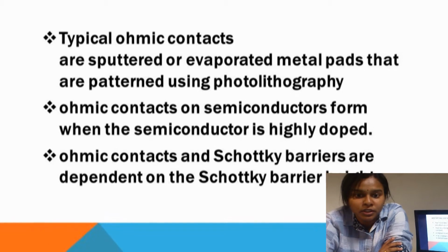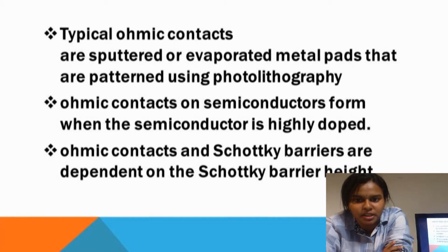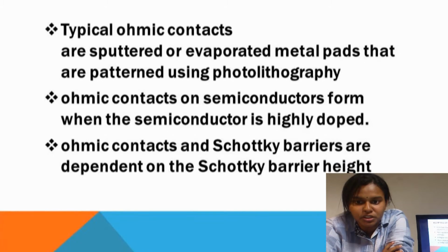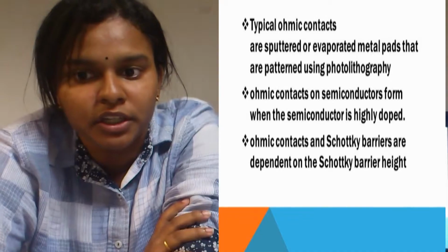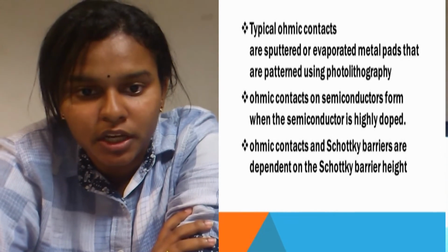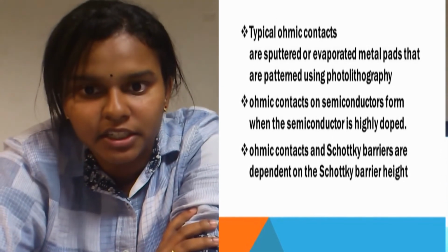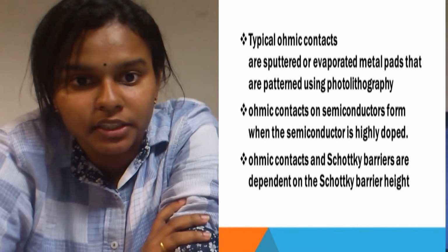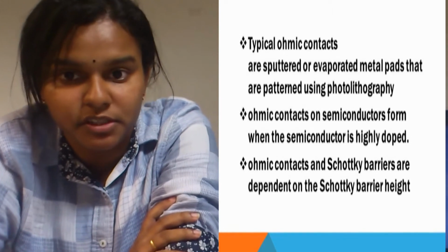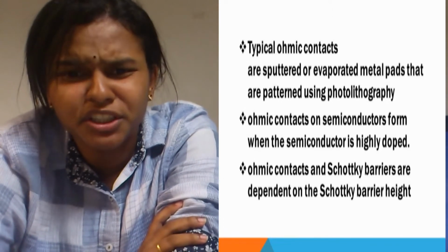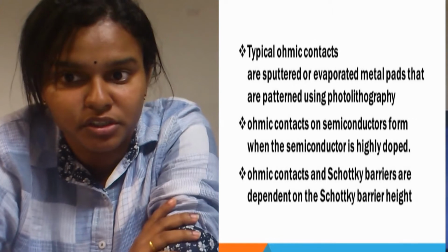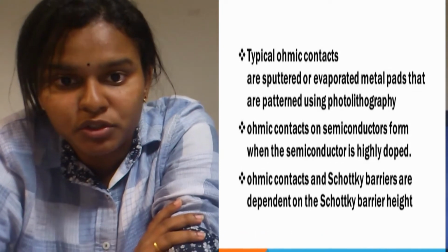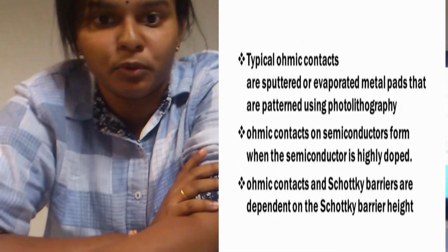It is usual to heavily dope the silicon region so that an ohmic contact is ensured. Suppose ND in the semiconductor is very large. The depletion region width at the metal-semiconductor interface surface becomes small. This process occurs in both directions, so the contact shows very little resistance and becomes ohmic.